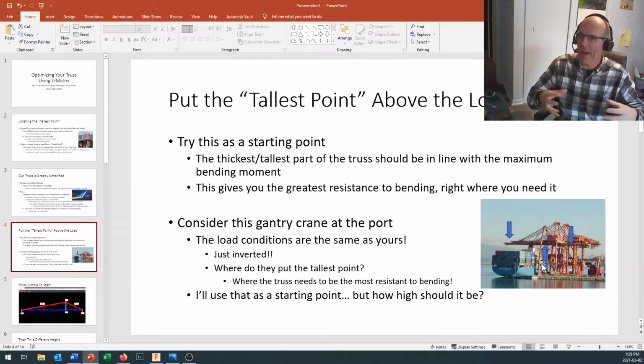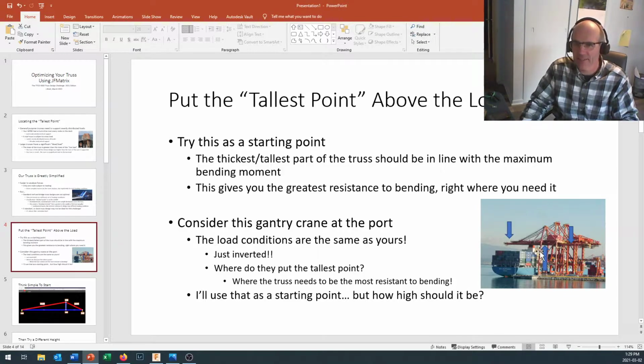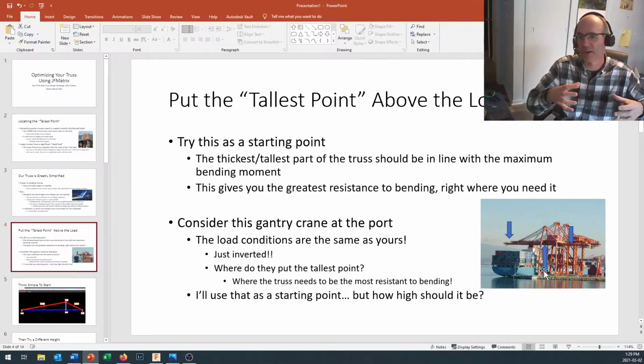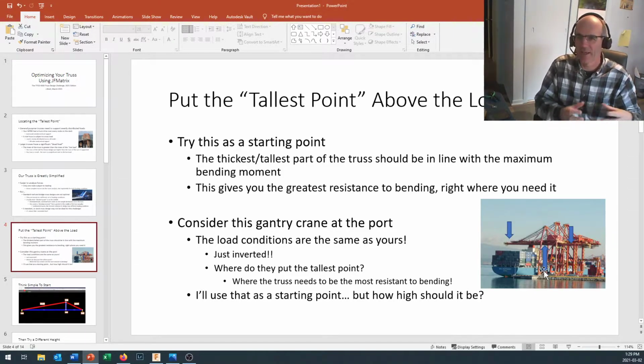They make those round, okay? You can see this is different right here. These members are cylindrical, round in cross-section, because they are going to be loaded in compression and have things pushing down on them. So they're trying to fight buckling. And with buckling, you never know which way it's going to pop out. So you make basically your moment of inertia the same in all directions.